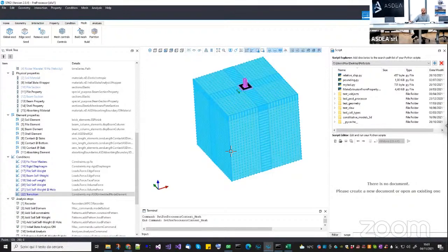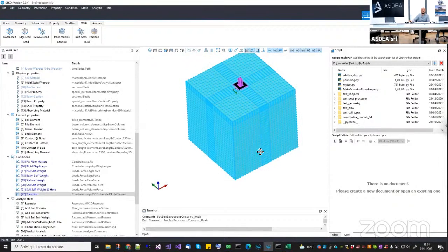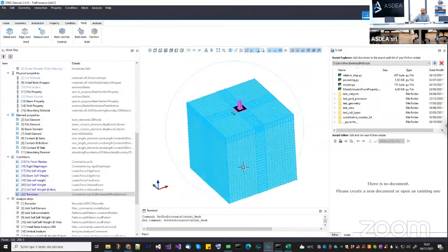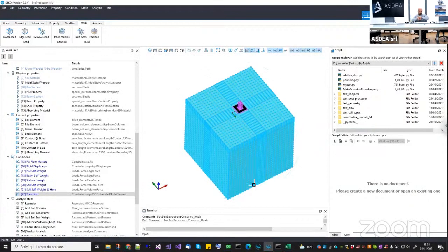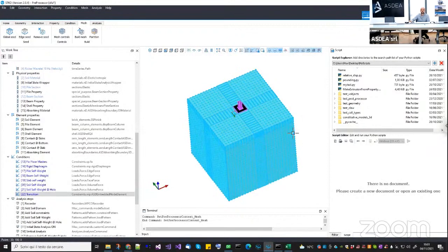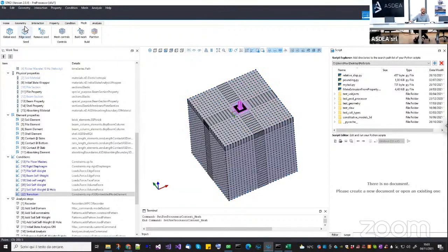So if I do a model which is less than the total wavelength, you will see some reflection, because the wave will be reflected from the top while there is still an acceleration entering the system from the bottom. So that's why I needed such a huge soil model. Let's try to see if I can do it in 15 minutes from now. And then, of course, you will have the entire model already done, okay?